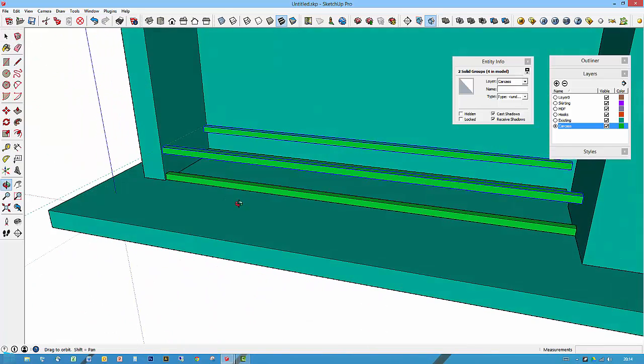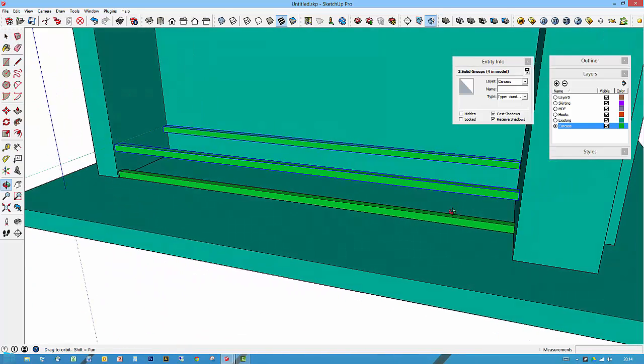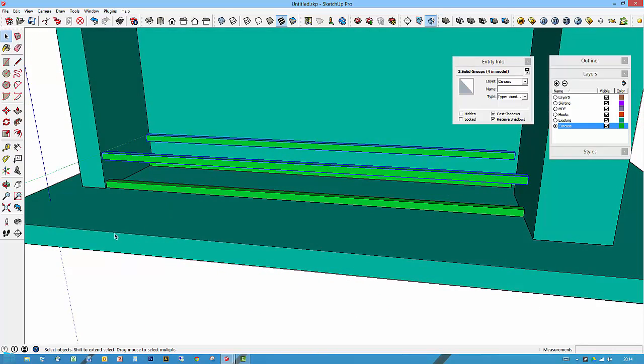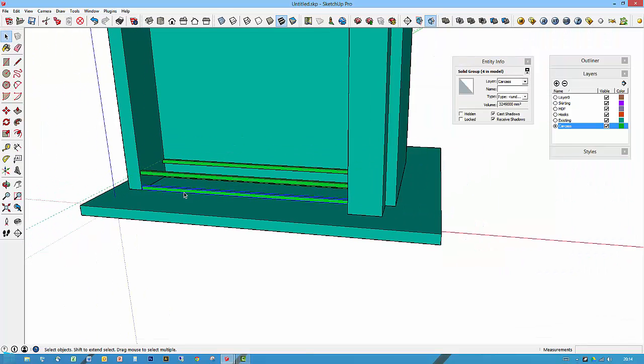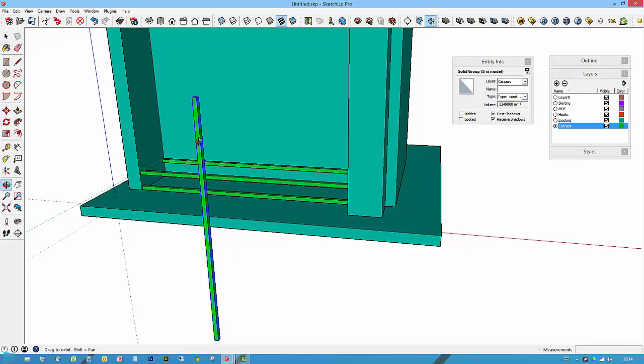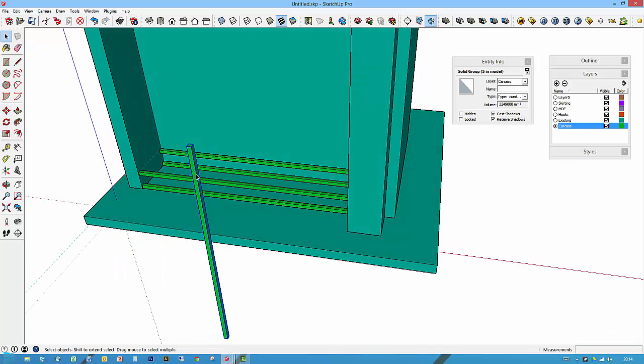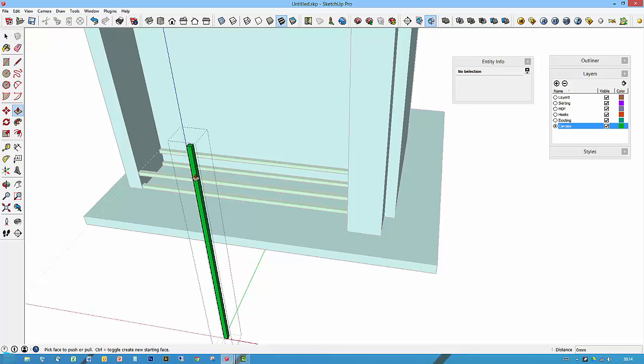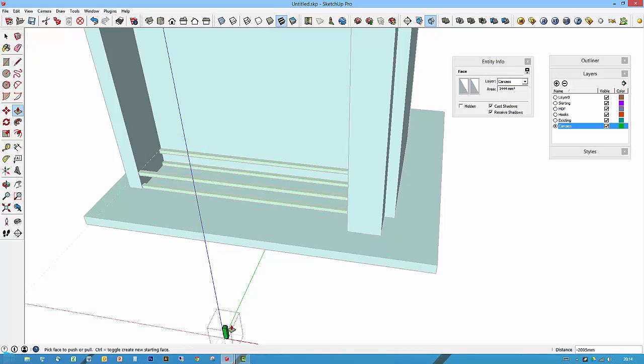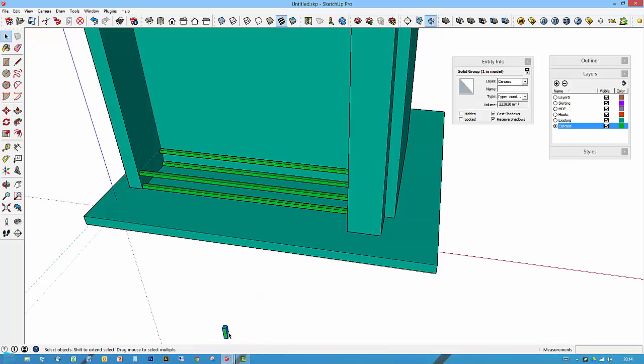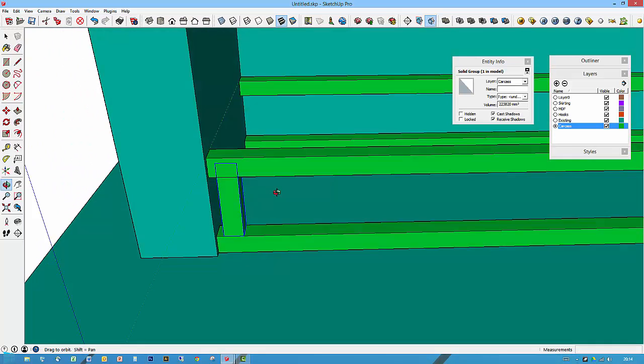We're starting to create our carcassing. Okay, so with this, we might as well take one of these. I don't want to draw another rectangle at 38 by 38. So I'll take that, rotate through 90 degrees, and then P for push pull. It's this icon on the toolbar, and then just drag that down. Something like that.